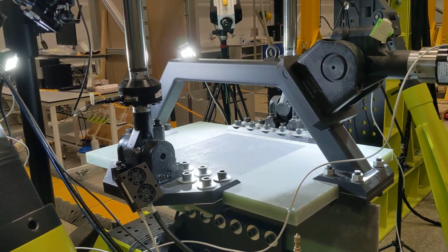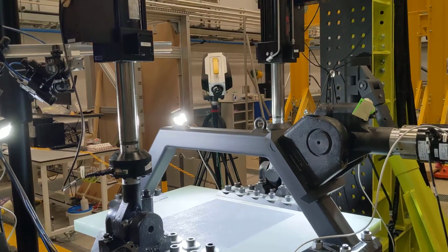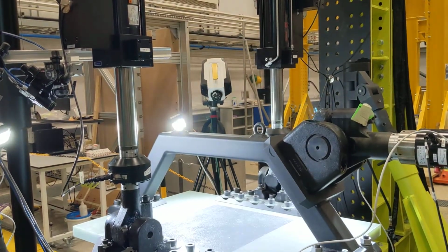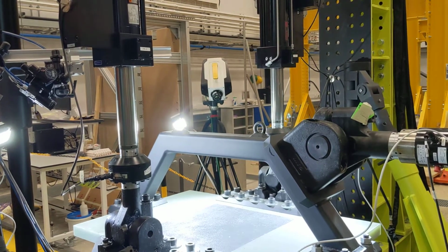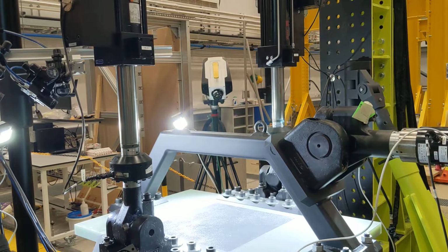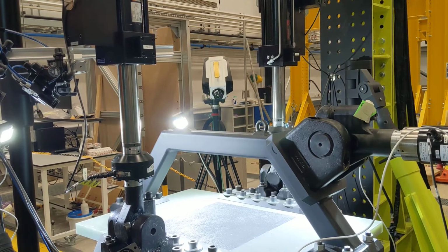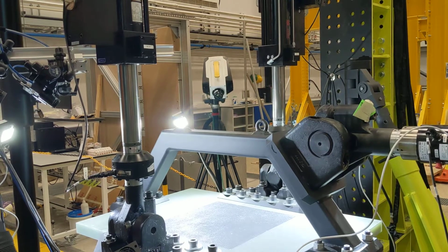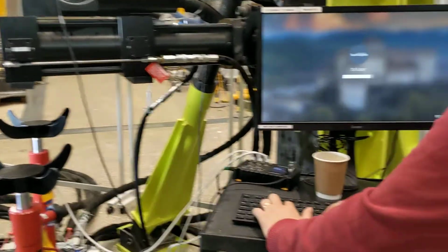We've also got two thermal imaging cameras, and what we can do with that is a technique called thermoelastic stress analysis. We're exploiting the thermoelastic effect, which is when you apply a stress change to a material, you also see a temperature change. So we can infer the stress distribution by looking at the temperature distribution across the field of view with our thermal cameras.